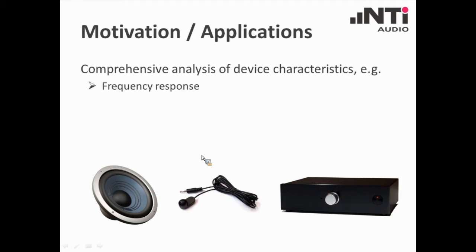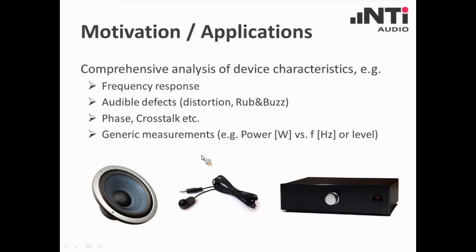Examples are the measurement of the frequency response or the detection of audible defects, distortions or rub and buzz in a loudspeaker, the measurement of phase or crosstalk and other related analysis, or even generic measurements as, for instance, the power versus the input level or versus the frequency.